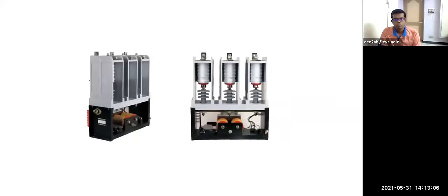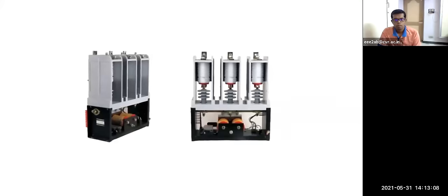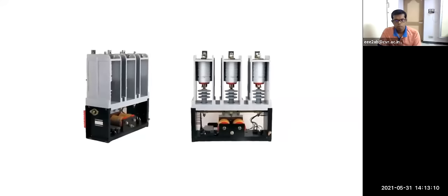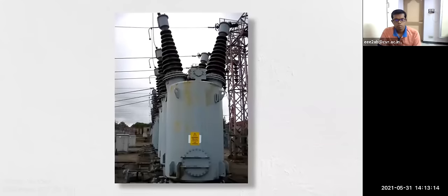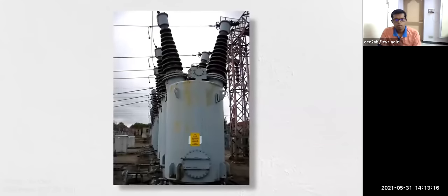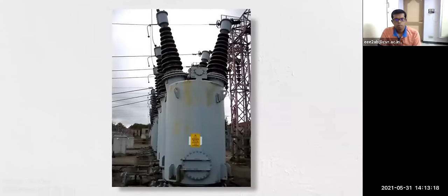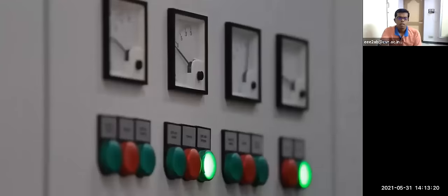For lower voltages, the circuit breakers can be located in a sealed container under vacuum to avoid electricity conducting in the air between the contacts. For higher voltage, breakers are often submerged in tanks filled with non-conductive oil or dense dielectric gas. These breakers give grid operators